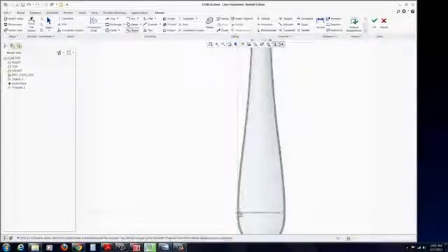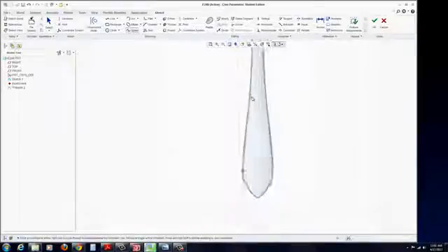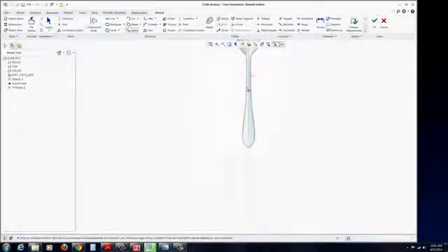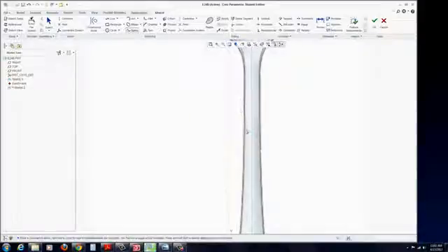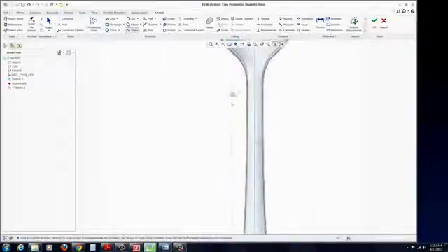Take the spline tool, now on that end there, click, and quickly get away from the center line so you don't keep snapping to it. And I'm a believer that less is more as far as spline points when you can help it. It's a lot easier to control and it looks smoother.